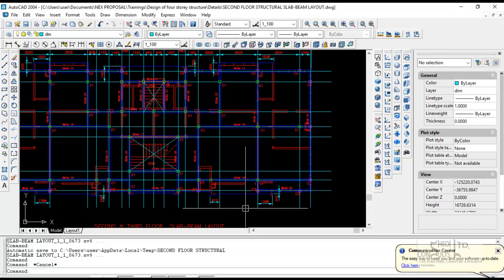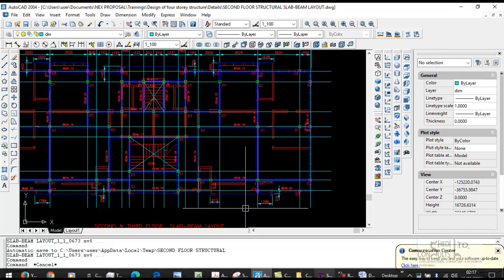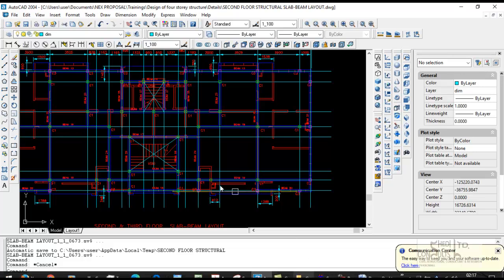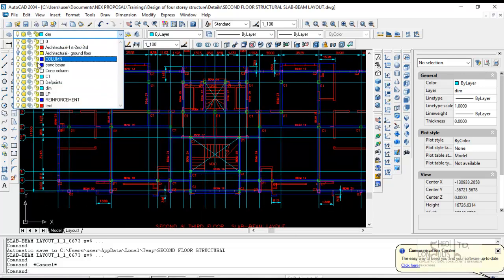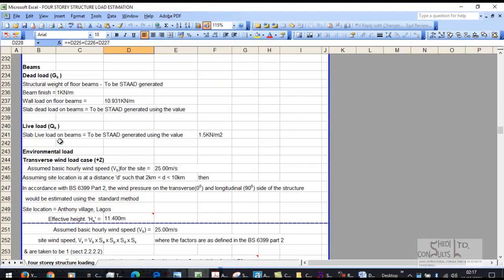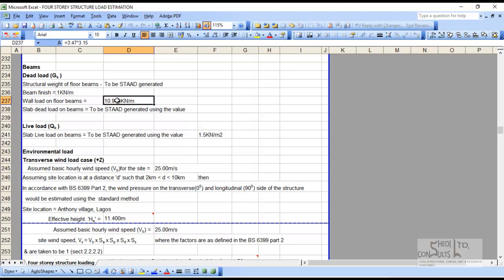So you must cater for that unforeseen contingency in structural engineering design. So you would assume that the beams are all carrying walls, and the wall load, like we have calculated earlier, using the specific weight of block work plus finishes, rendering on both sides, 12.5 millimeter rendering on both sides, each weighing 0.3 kilonewton per meter square as provided for by the code.